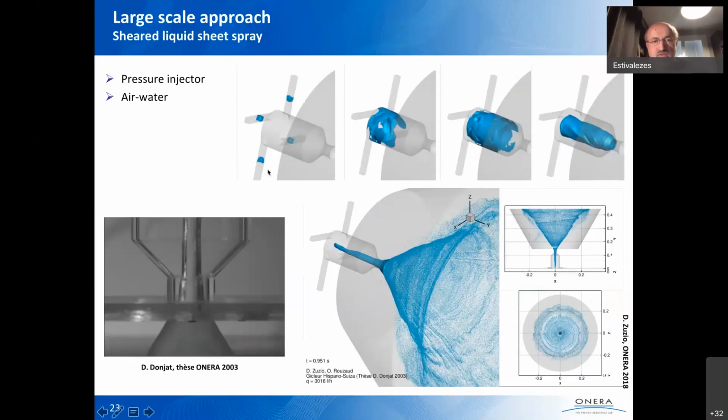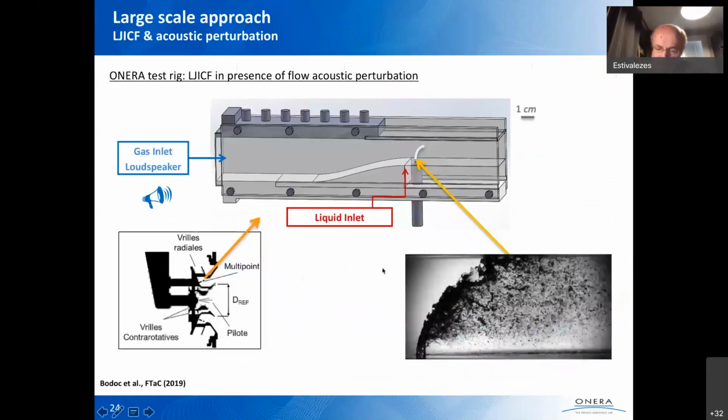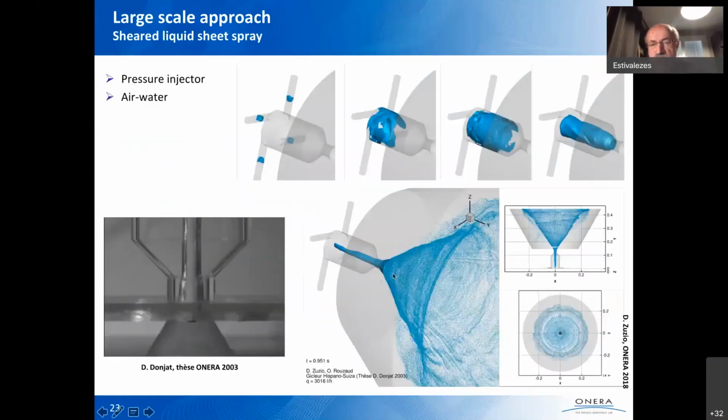So you can see the four liquid entrants. So this is in rotation. Okay. So the liquid bulk phase rotates. So you can see this here. And then when you arrive in this zone where the grid is less refined than this one, so you will diffuse what is called the volume fraction, and then produce droplets.